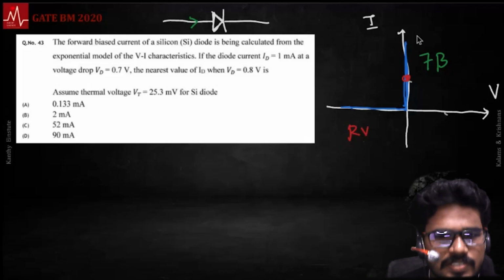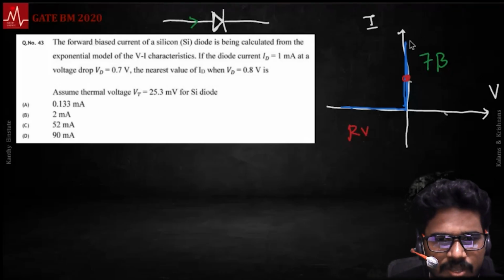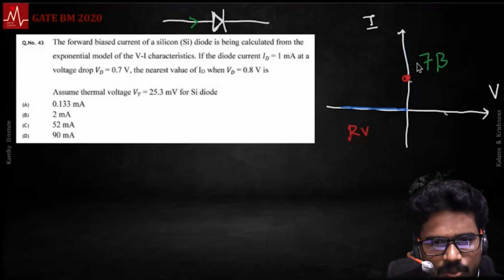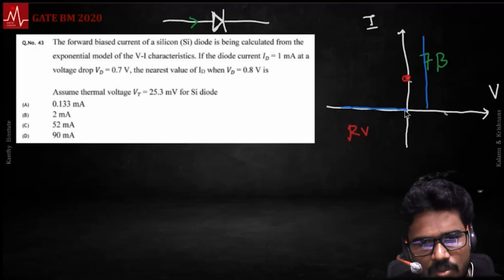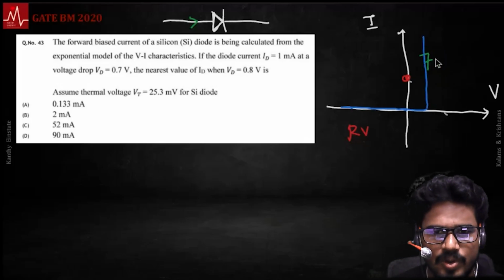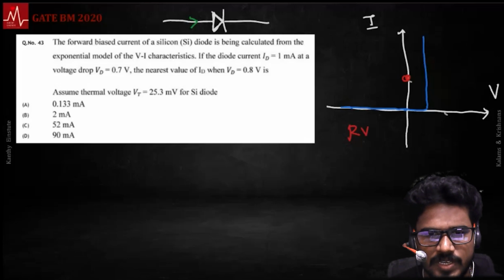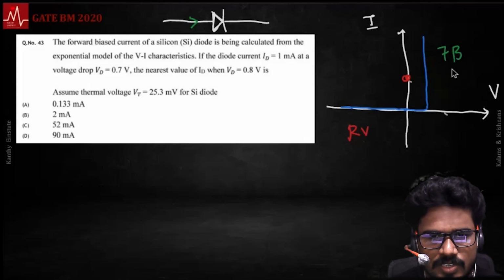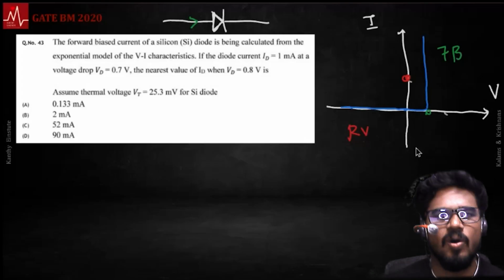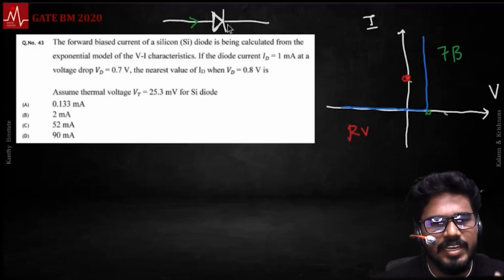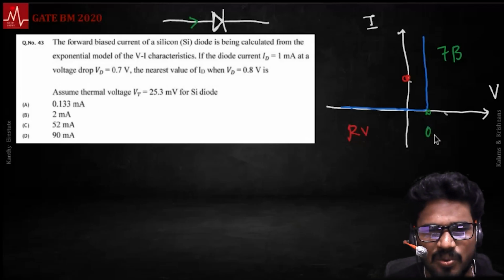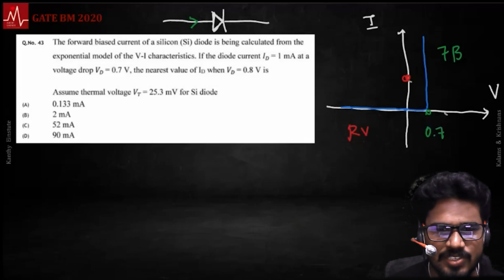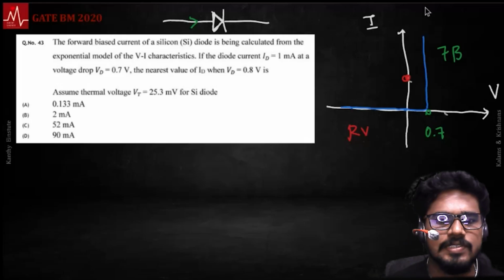And sometimes this is the ideal model, the simplest model. There is a change in voltage across the diode, so you slightly write it this way. There is a threshold voltage here, right? You approximate it this way in the forward bias. This is a threshold voltage. Even in forward bias, in a real diode, the potential drop is non-zero. So this is roughly 0.7 and all that, depending on the diode, silicon, germanium, whatever it is.